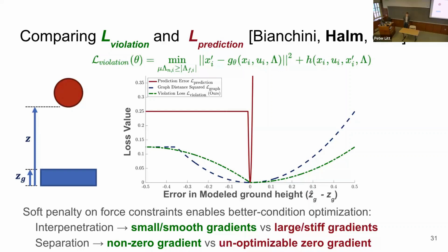I mean, that's certainly true, and we're going to see on real data that has a low amount of elasticity. We identified a coefficient of restitution like 0.1. It can have a significant effect to take those assumptions away. I don't think it's fundamental to this approach to be assuming inelasticity. We did have a master's student who worked on an elastic version of this that had similar optimization characteristics. It's just not something that we've prioritized over the last couple of years.